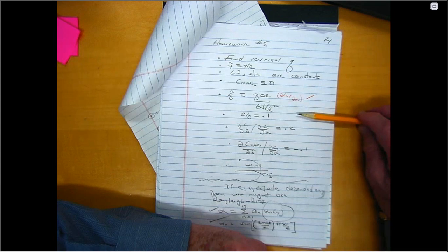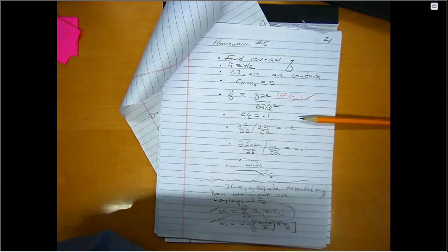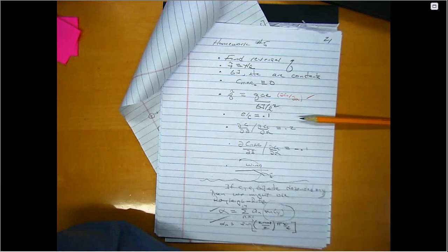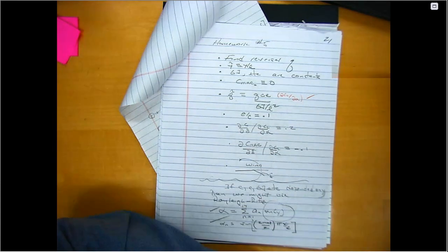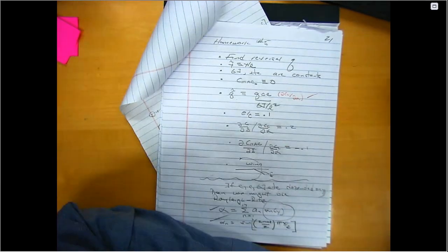Yeah, because remember what E is. It's the distance from where the lift acts, the aerodynamic center, to the elastic axis. And it's that lift that gives you a moment about the elastic axis that creates divergence. So if I were to set E to 0, I would drive the divergence Q to infinity, which probably means it's greater than the reversal Q.